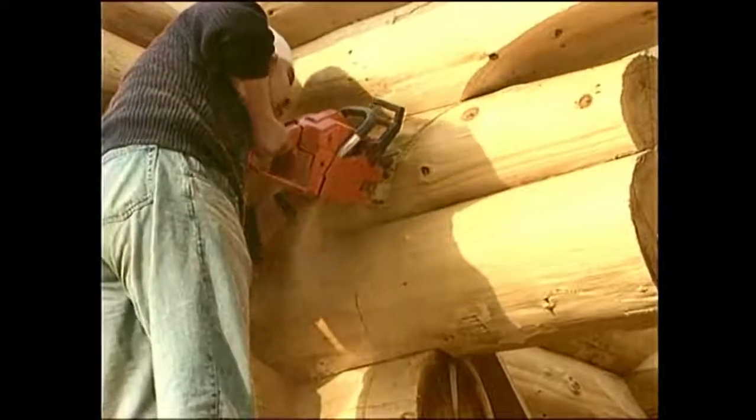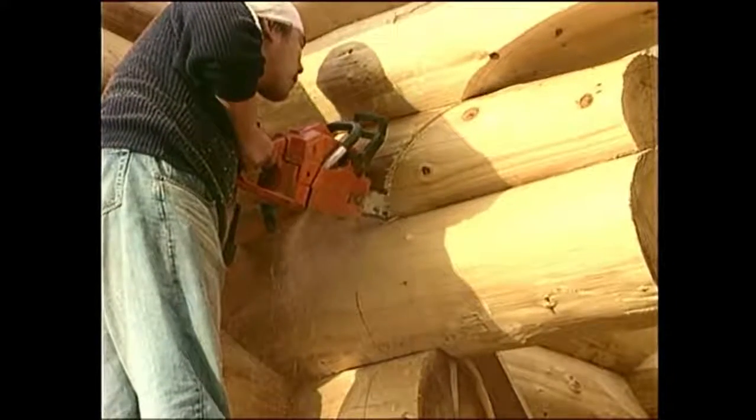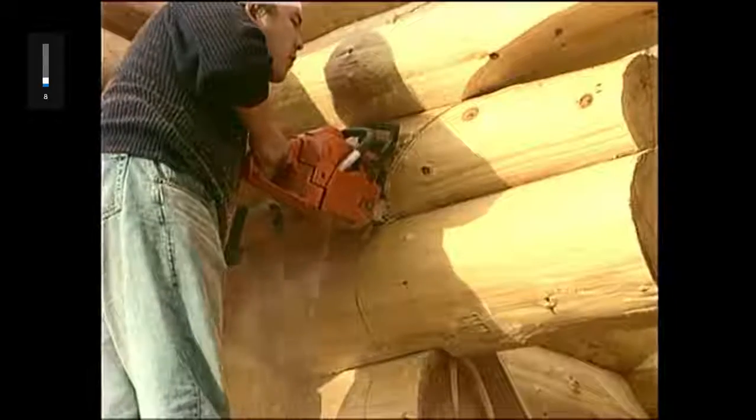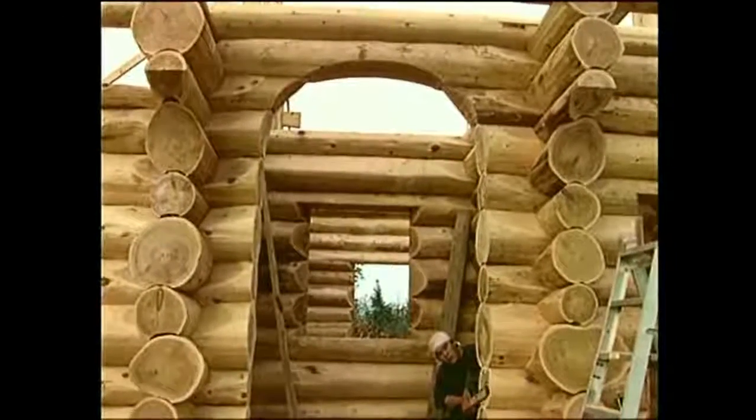1. Cut out any archways. Be careful to keep the saw at right angles to the wall. Make a practice cut at least 6 inches inside the final cut line if you've not done this before.